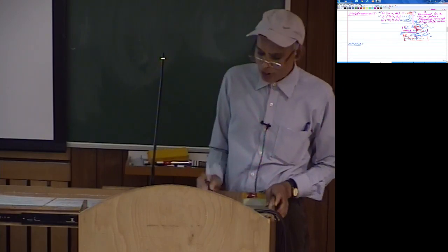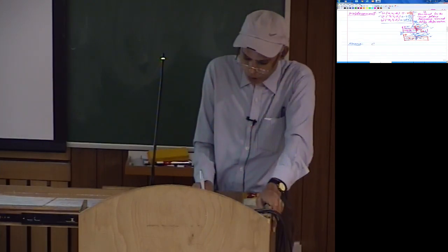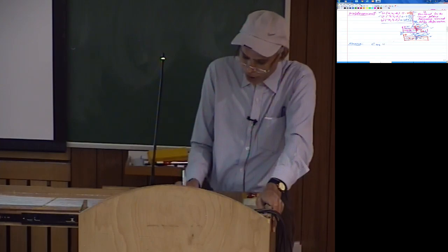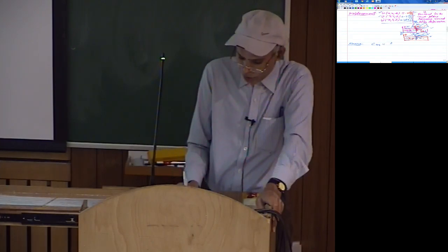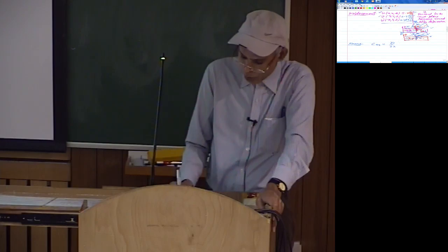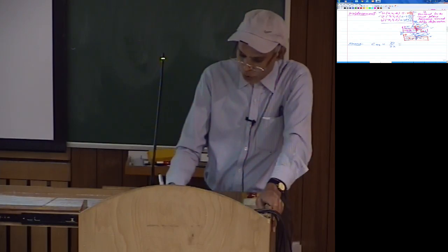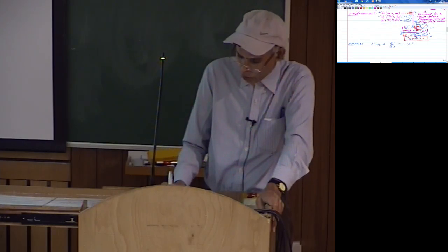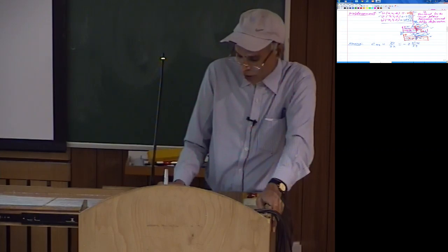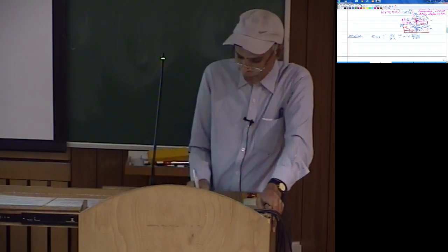And the strain is similar, the same logic. You have epsilon xx, which is del u by del x, and del u by del x, as you see from this expression in terms of w, this is u, and here what you have is minus z into del 2 w by del x square.